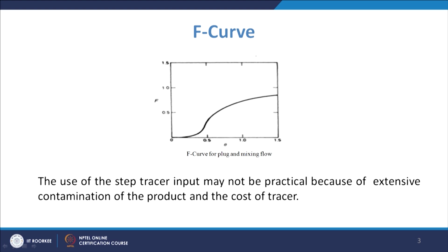Now, use of the step tracer input may not be practical because of extensive contamination of the product and the cost of tracer. So, it is not very much in practice, except we can certainly go for the numerical analysis of these processes where we do not require these expensive tracers and their use. But you do not prefer that, because if the tracer is going continuously into the molten steel, that may even contaminate the steel.